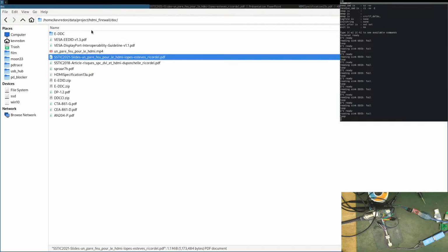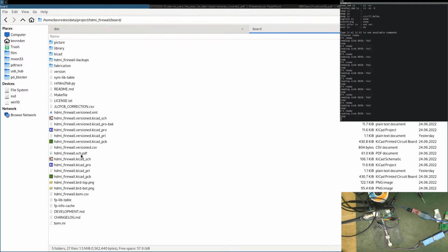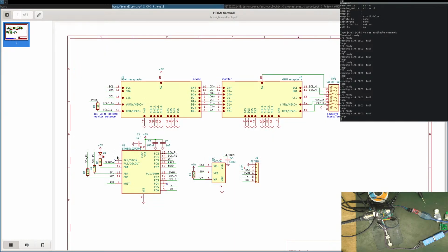If we have a look at my board layout, here I'm using a 1.5 kilo. And this is actually for the sources, the source side, not for the sink. And here I'm acting as a sink. So this is already wrong. This I need to fix. I didn't print anything, did I? No, I didn't print it.